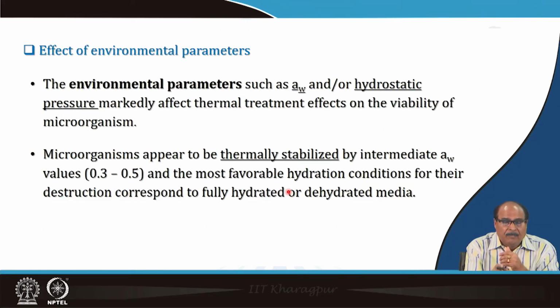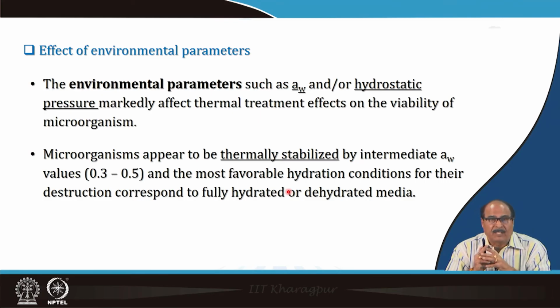Environmental parameters like water activity and hydrostatic pressure markedly affect the thermal treatment and its effects on the viability of the microorganisms. Microorganisms appear to be thermally stabilized by intermediate water activity values like 0.3 to 0.5; that is, if water activity is brought below this, microorganisms are completely sterilized, and the most favorable hydration conditions for their destruction correspond to either fully hydrated or fully dehydrated media.